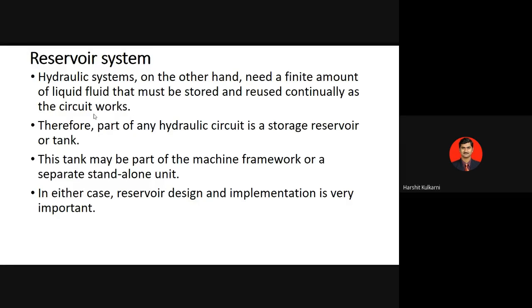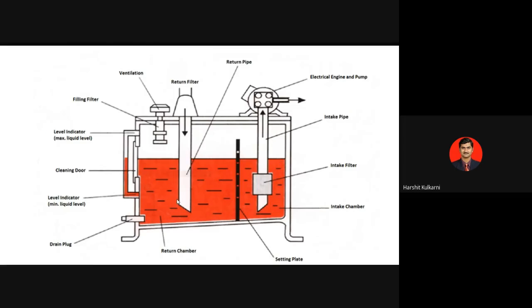So what can be the question on this? They can ask you a question like, sketch and explain a typical reservoir system for a hydraulic circuit or for a hydraulic application. A typical reservoir system can be explained with this diagram. You are supposed to draw this diagram, so please practice it. It's a simple diagram with different elements. This is an intake chamber. In the chamber we have the hydraulic fluid that will be continuously stored, and there will be a level indicator here, showing how much of the tank is filled with oil.